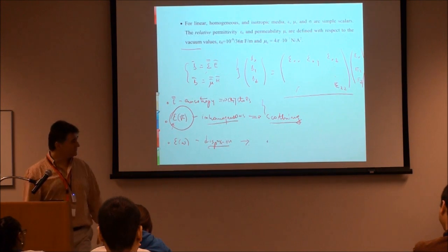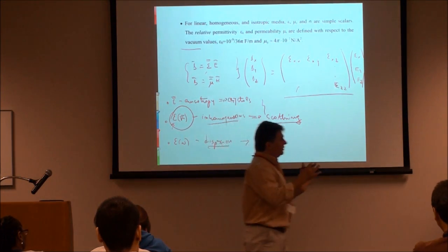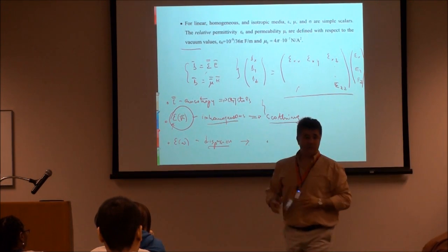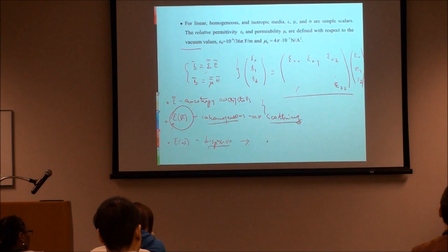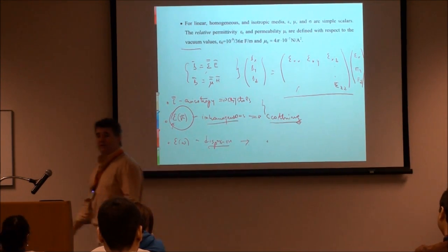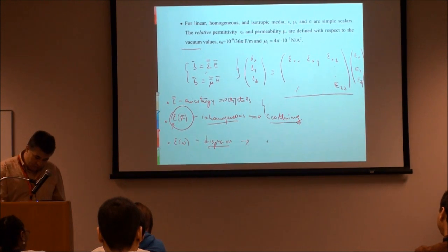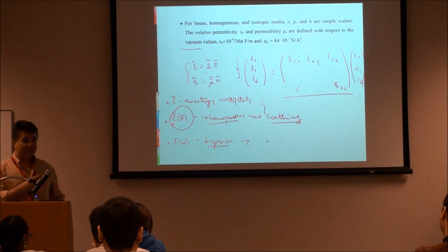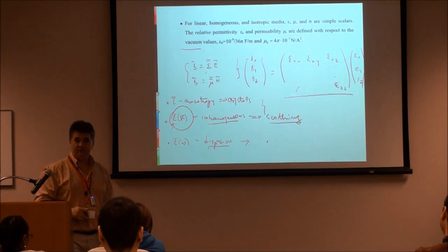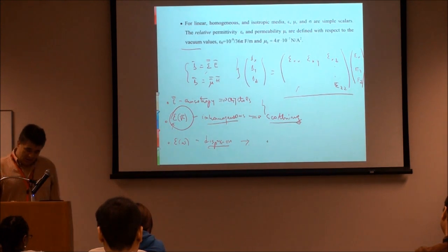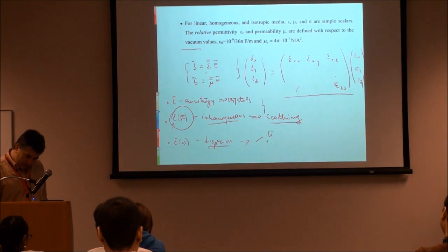Fiber optics, yes. You want to compensate the dispersion as much as possible such that your pulse stays the way you put it in. If this spreads over to the next pulse and the next pulse and so on, your internet is going to get messed up, right? So dispersion is very important in the time domain in communication. There is no question about it. But also, it somehow sneaks into the spatial domain when you do imaging. Okay, so let's say time domain.